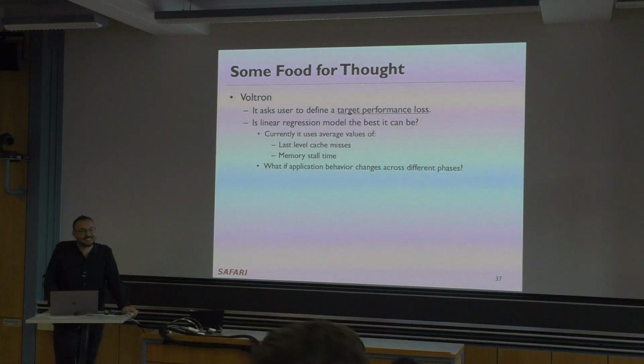Yes. I think this method will be more effective when we have a lot of switching, because if we see the power calculation, the dynamic power consumption is the one that depends on the voltage square. Yes. And it depends directly on the frequency of the operation. Yes. And it has the activity factor attached to it. Yeah. So when we have a lot of activity in the circuit, the power consumption will grow linearly with the activity. But with the voltage, it will grow quadratically.